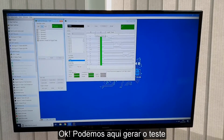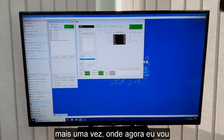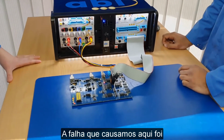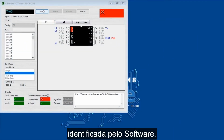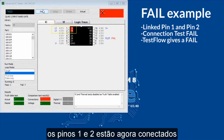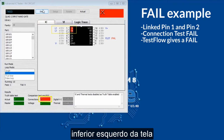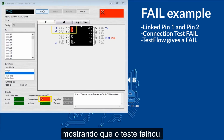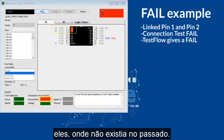Okay, sure. So what we can do here is start the test once more. And then I could cause a fault. Oh, okay. So what we have done here is, as identified by the system, we have linked pin 1 and pin 2. We have L1 on either side, meaning these two pins are now linked. Okay. And as you can see here in the bottom corner, our connection test has now failed. The instrument itself has given us a cross, and so is our test flow instrument telling us that this test has now failed because the connection test is not as it should be.